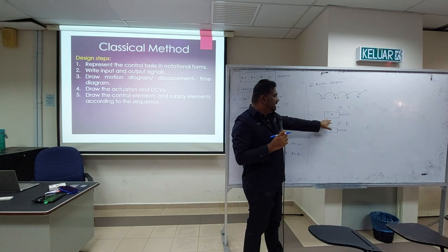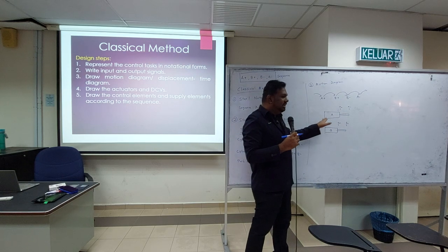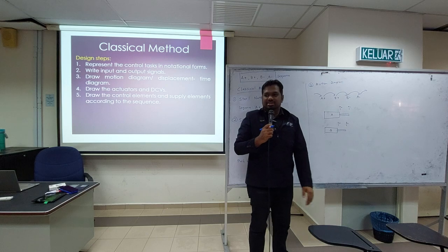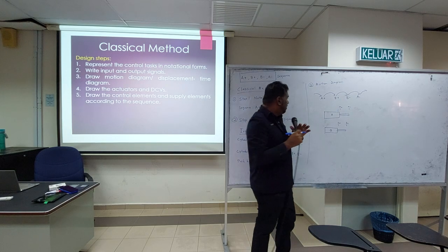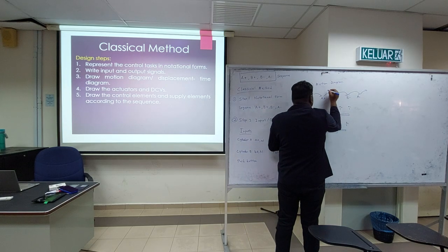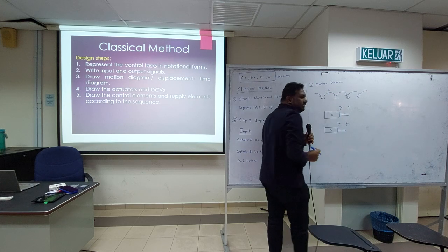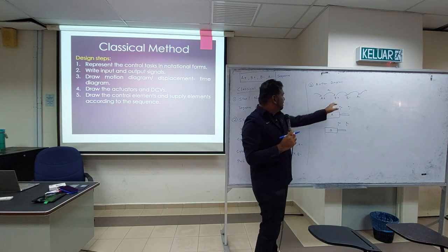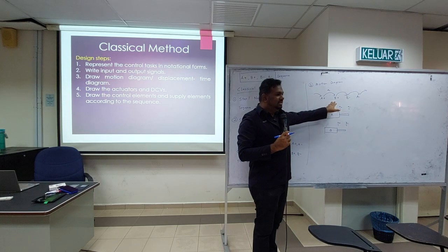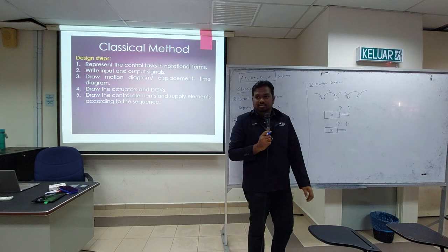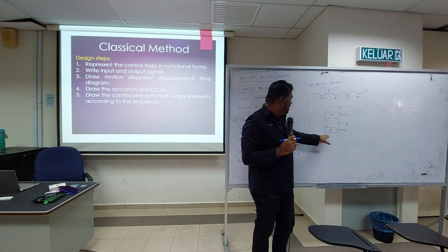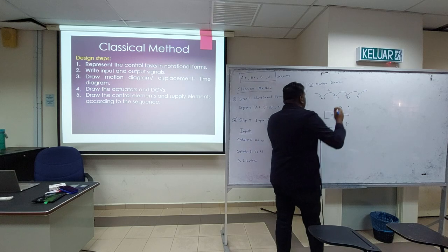Okay, so cylinder A plus, meaning cylinder A fully extends, so which sensor will be on? A1. So A plus, this one is A1. Okay, after B plus, which sensor will be on? So B plus extends, B1 will be on. This is B1.